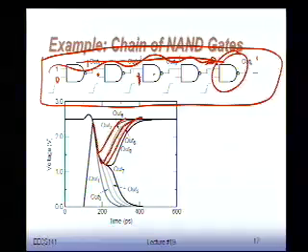Just as we would see, for instance, in adders. If you have a ripple adder, that's exactly what you see, right? All the primary inputs are applied immediately, and the carry kind of ripples through. And before the carry arrives, you already might start going in another direction for the sum output, for instance, or for the carry output. So that's a typical glitching problem.